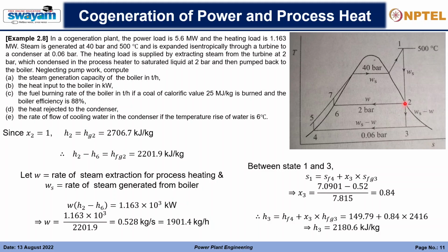So that will be a lower amount of energy generation, right? But the thing is that it is quite simple, the complexity is very less, and the maintenance cost is also very less. So if you are working in moderate industries where so much complexity and sophistication is not needed, go for the back pressure turbine. If such a desired effect is required, then you need to go for better suitable options like the pass out turbine.